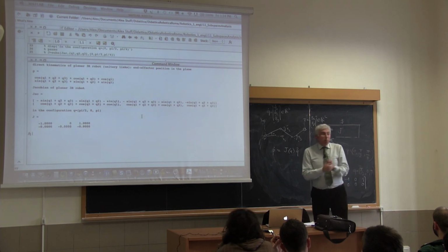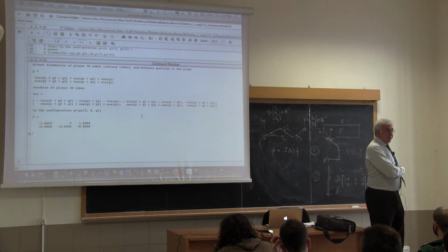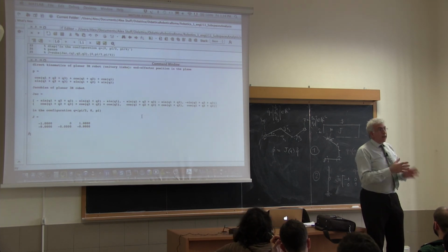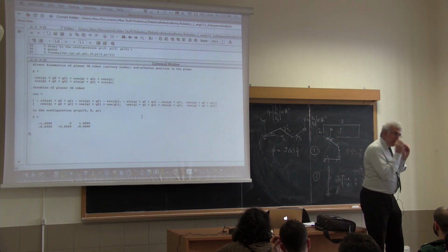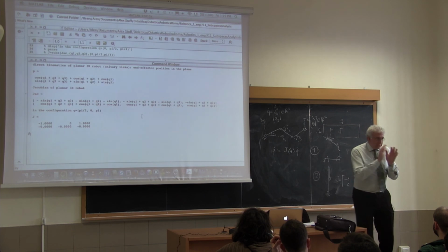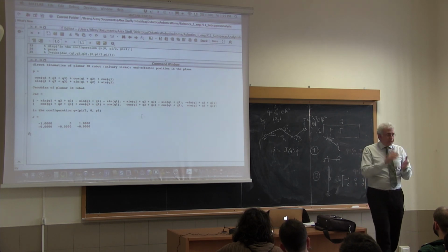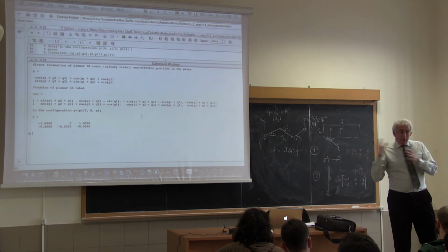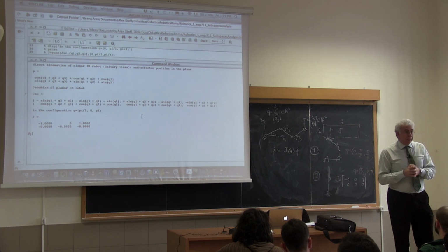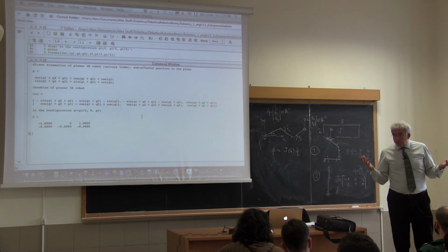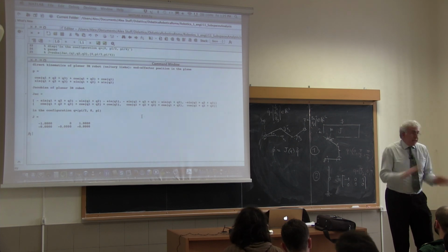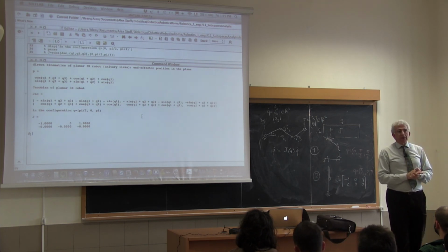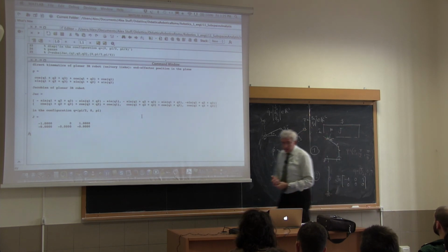that I can depict. One may say, well, but I'm very unlucky to be in this situation. Okay, so it's only very local. What happens? Well, as a matter of fact, even if I'm not exactly in this situation, but pretty close to this, I will have problems in inverting the kinematic mapping. So velocities that are close to being unrealizable at the Cartesian level will need a huge amount of joint velocity to be realized. So in practice, it's like being in a singularity. So it's not just the point, it's around the singularity that problems arise, and this is why we need to study these cases.